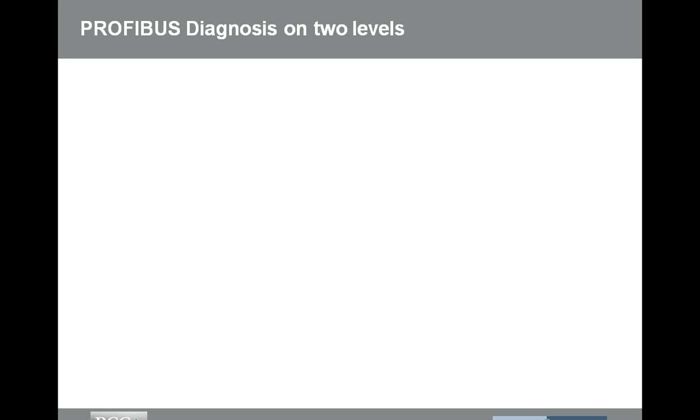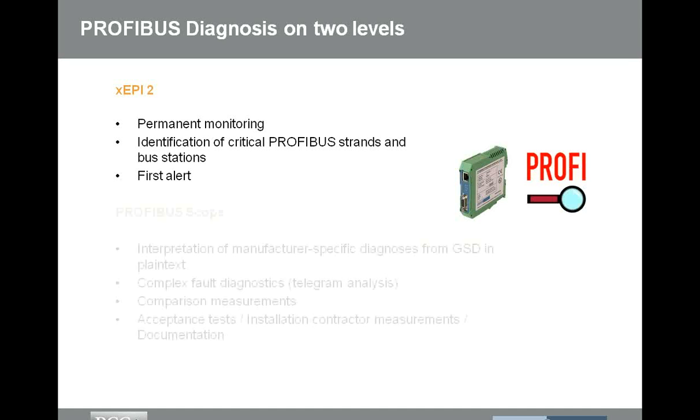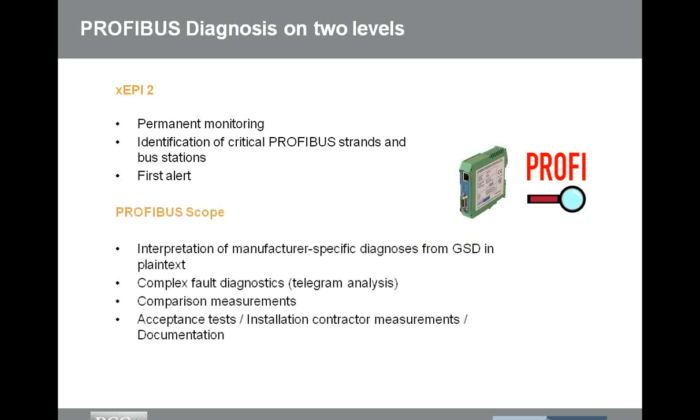When we talk about Profibus diagnostics, again, there's really 2 different levels. There's the permanent monitoring, which is what this XEPI tool does. It's going to identify a critical Profibus issue quickly and give you kind of a first alert situation. And then if you utilize the Profibus Scope product in conjunction with this, you can actually connect up and, using the GSD files, get complex fault diagnostics, actually see the telegrams going across the Profibus network, do comparison measurements, acceptance tests, and that type of stuff.